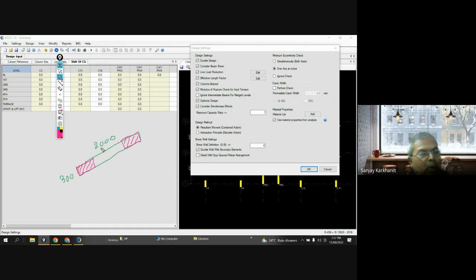So the entire shear wall is considered in these three parts. These two parts will be braced by this middle part, and you can see that this will act as a column, this will act as a column, and it will be braced throughout the length of the column by this middle part. So this is called a boundary element, and many times you may find boundary elements something like this. That depends on what type of loading you are going to resist through the shear wall.